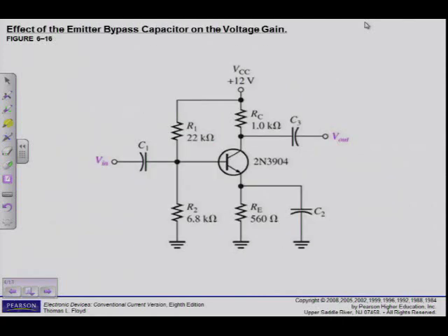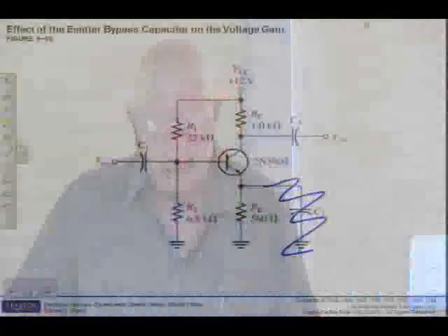Alright, just below example 6.4, voltage gain without the bypass capacitor. Here you can mark it. I've already told you and I showed you on the board here. You can see how my formula, my equation changes. Now it's equation 6.6. If I do not have the bypass capacitor, then my formula changes to equation 6.6. That's why I say you always have to look at the circuit that you work with.